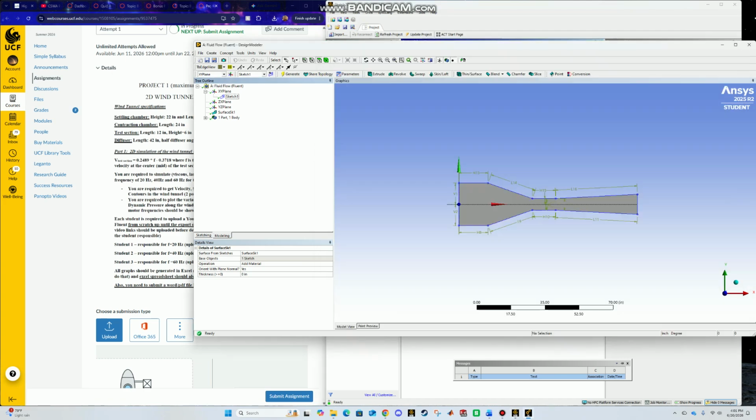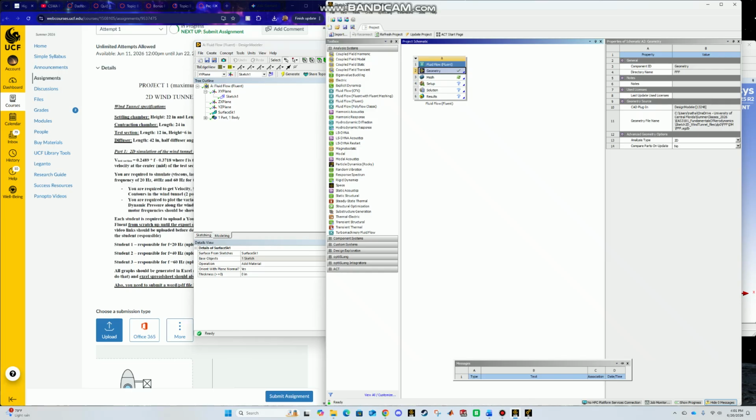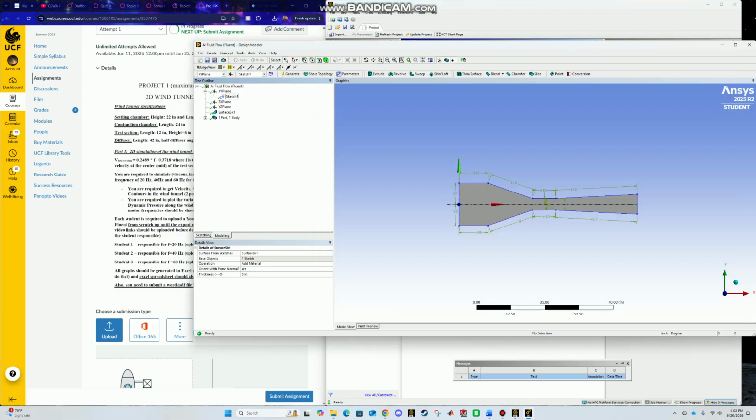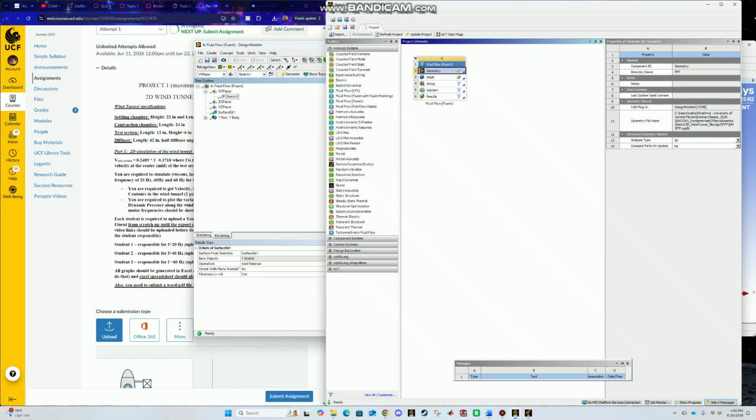So it's all generated. We're pretty much done on this part. We're going to update it in our workbench before closing it, just in case. I believe you right click, yep, and then you hit update. Got a little check mark, it was already there, but we should be good now on this. So we're going to go ahead and close the sketch now that our workbench is updated. That'll probably take a second for my computer, and we're going to open up the mesh tool right here.